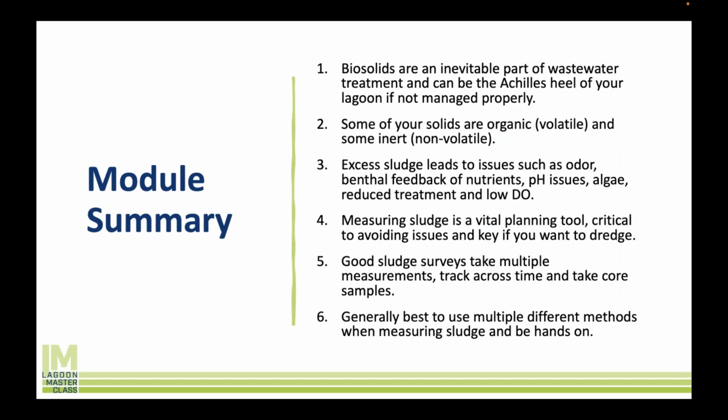So, takeaways. Biosolids are just an inevitable part of any wastewater treatment process, right? And if you don't manage them and prepare to manage them within a lagoon, they are really the Achilles heel of lagoon systems. They will hurt you over time. So it's really important that you pay attention to it, that you understand it, you understand how to measure it, and how to project forward and plan to remove those biosolids and manage them.